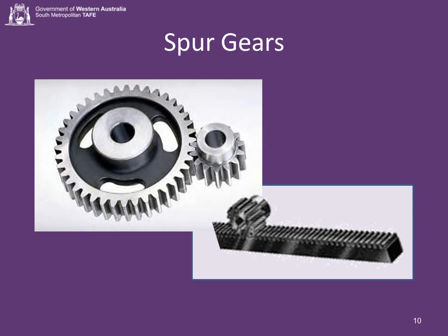Usually spur gears are used for moderate to low speed applications. Rotation of spur gear sets is in opposite directions unless one or more idler gears are included in the gearbox. Typically spur gear sets will generate a radial load opposite the mesh on their shaft support bearings and little or no axial load.